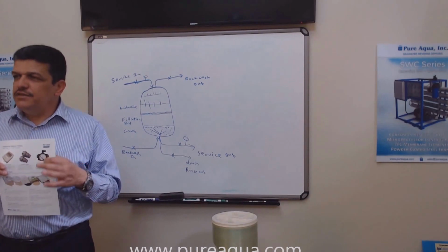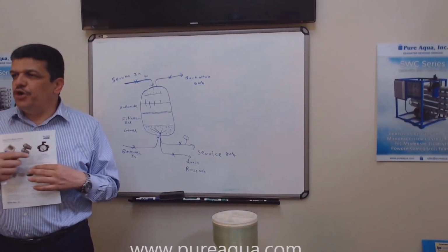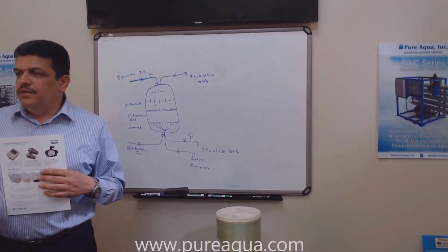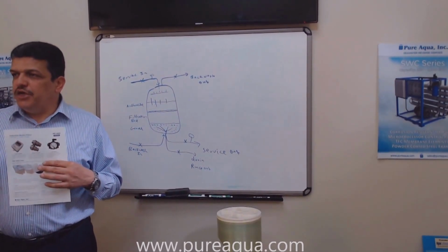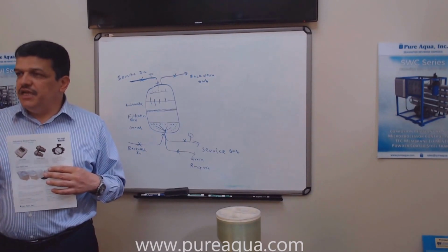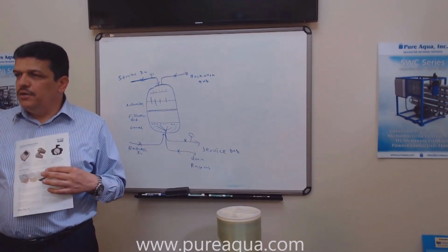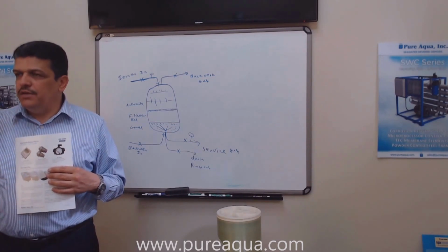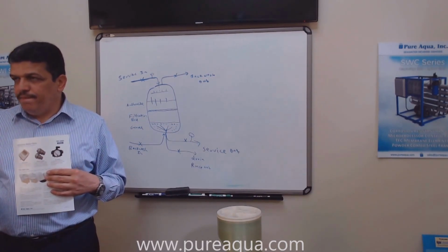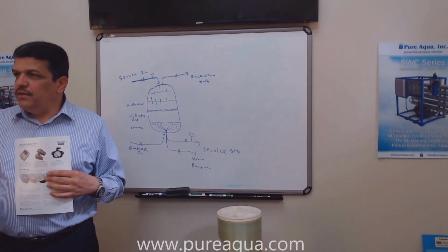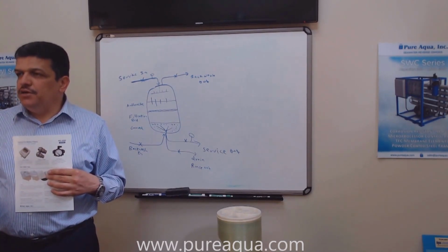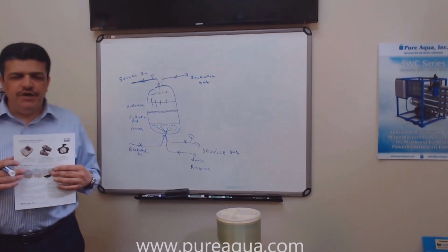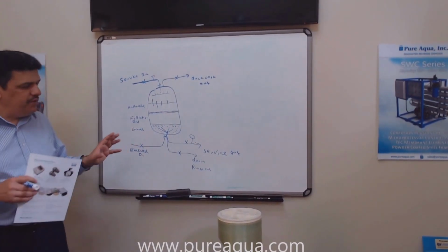So that device is programmed or set at, let's say, 12 psi. Whenever it triggers at 12 psi, it gives a signal to the controller or a stager or a PLC. It's time to do a backwash, and it starts immediately. Now that control panel or stager will send a signal to the backwash pump.